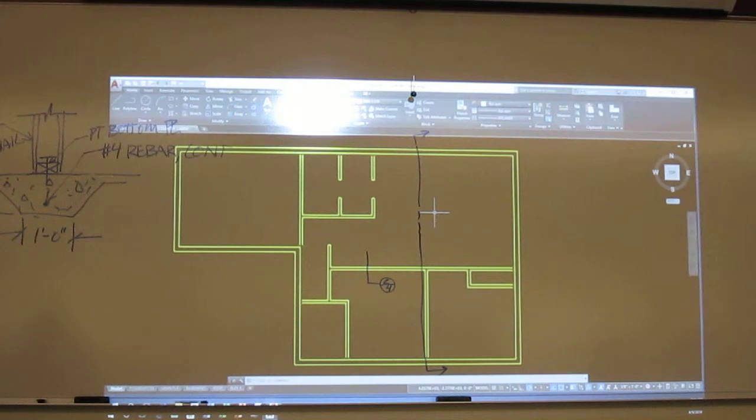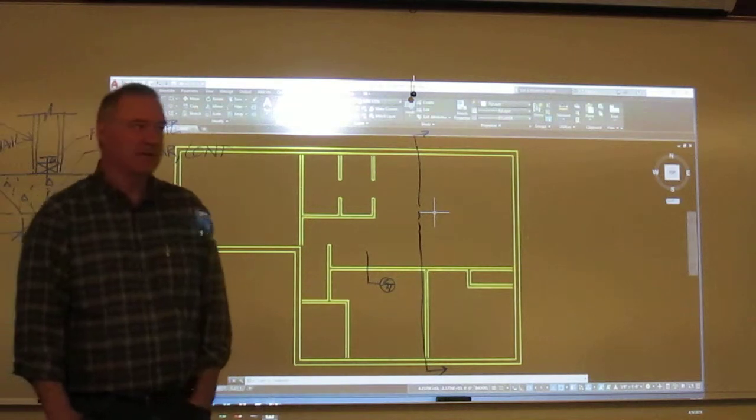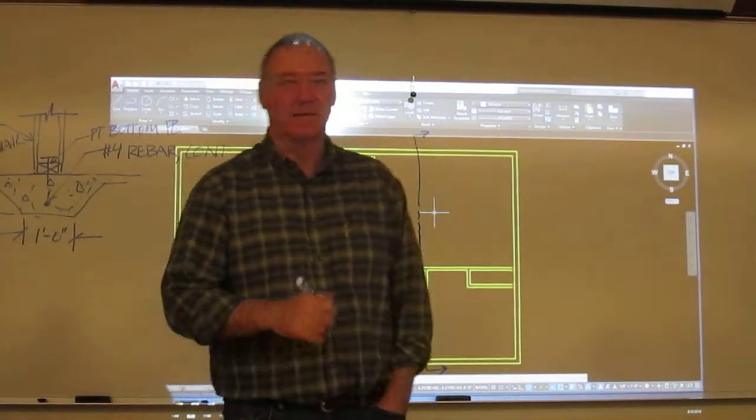Yeah, that was good thinking there. Do we need to protect this from the concrete? Yes, we do. Now, generally, we're not going to put like felt or some membrane down there because we want that glue to grab onto it. The glue is actually much stronger than those nails are.